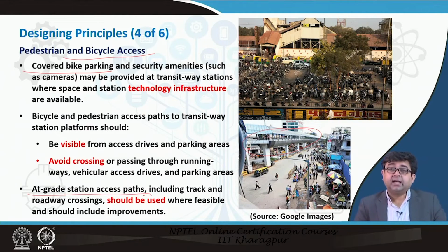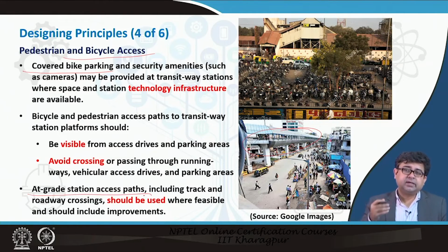These are more attractive, because once you provide grade separated access, people with luggage usually do not want to climb up the stairs and climb down the stairs with it. Old people would not use it. Even people in a hurry would not use it. They would say that, well, I have minimal risk if I cross the road at grade versus if I take this.